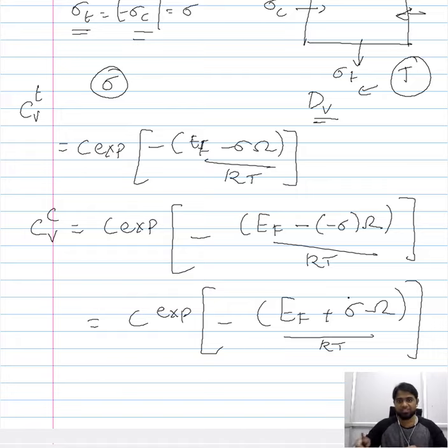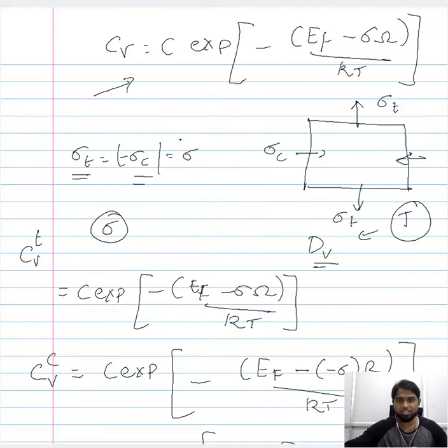So we have an expression for it, the common expression, we have written it down here. Now we consider a system that is similar to one we have during creep testing. There is a tensile load applied to it, and we are holding that material for a definite period of time. Under that condition, because of the Poisson's effect, you have a compressive load acting along the lateral direction.